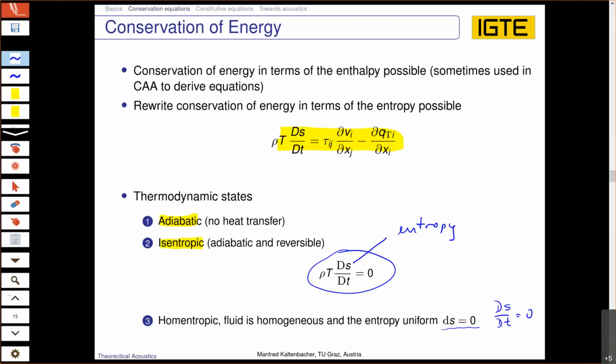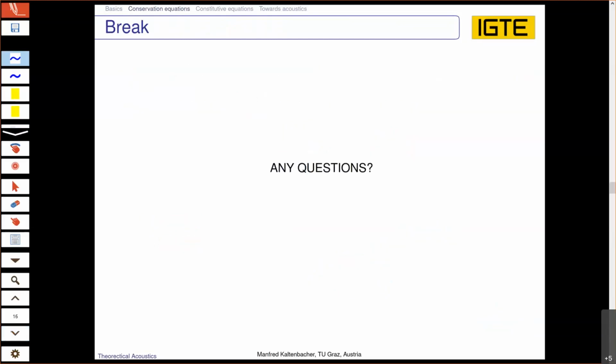Okay, in our case, we can really simplify it because we will not consider any generation of acoustic waves or flow around obstacles in air, or flow through a structure. So we have confined flow through a pipe or whatever in this sense, and we consider the subset where more or less the temperature is constant. We get rid of the energy conservation because it is fulfilled. And as we will see soon, this has an impact on the relation between the density and the pressure.